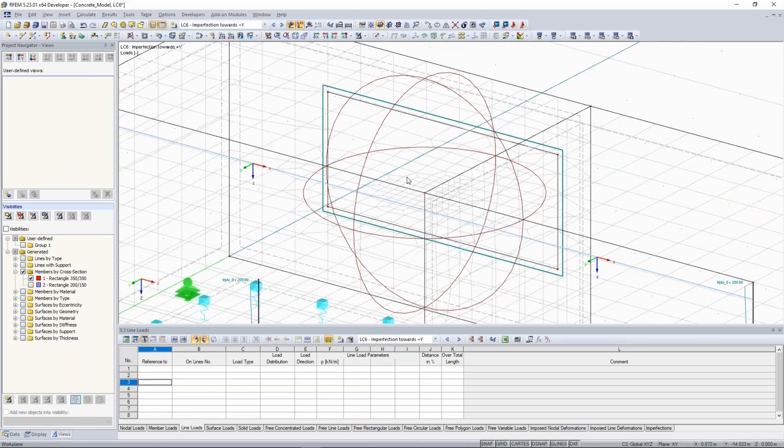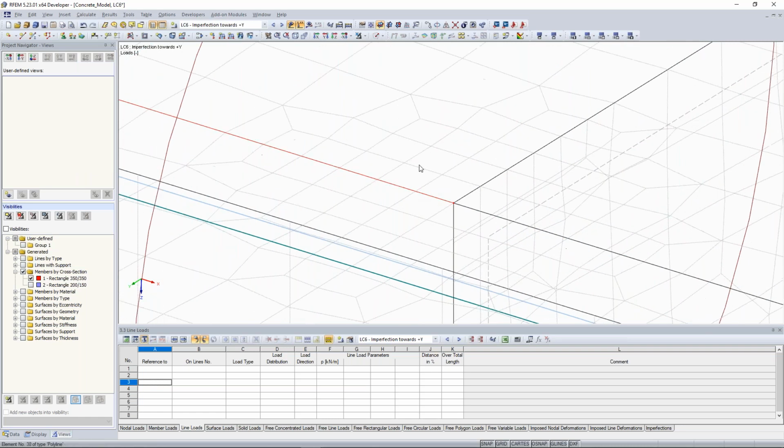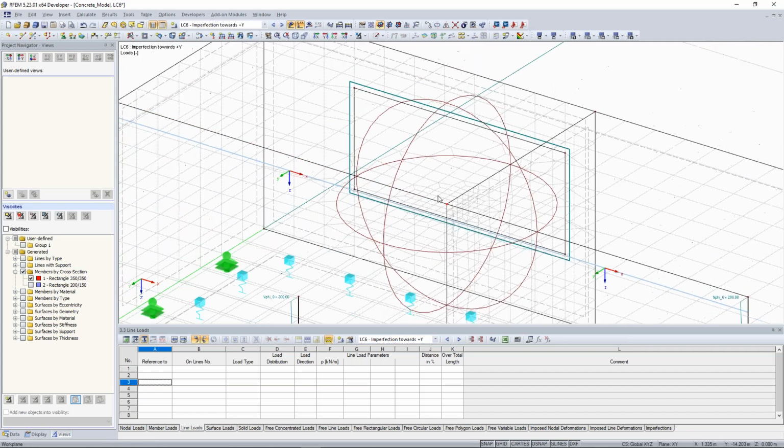And when we use here the FE mesh refinement, you see we made an FE mesh refinement, and here is the inner length, 0.1 meter, and it becomes bigger and bigger up to the 0.5. And it's up to you how to do that.